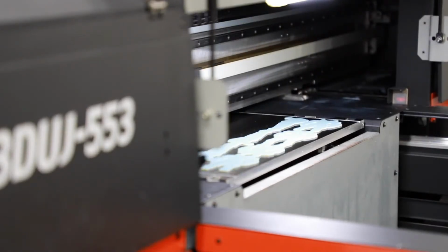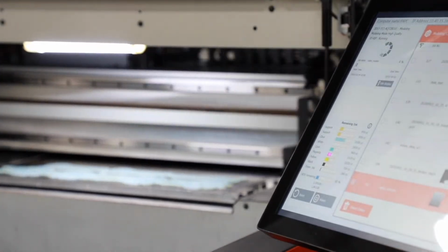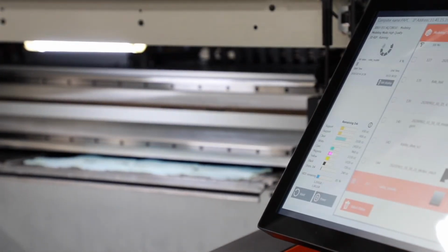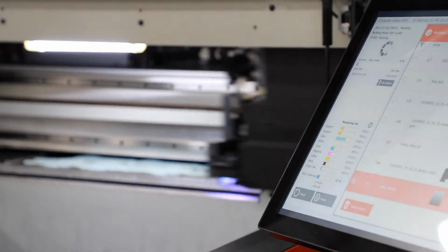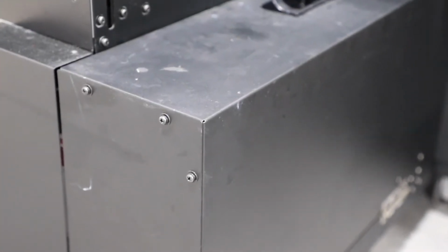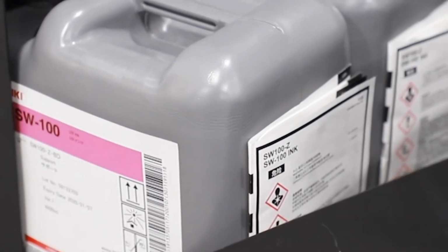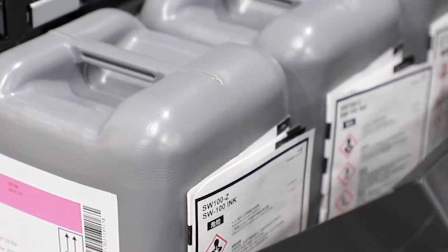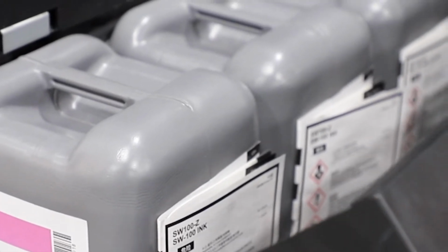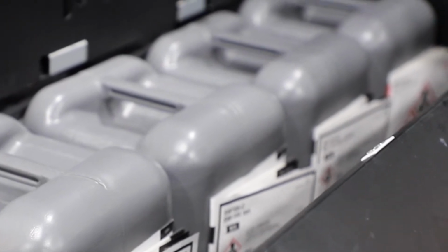Inside the machine, there's a series of 5-liter ink tanks. The printer actually prints using the resins from those tanks. This way, you're able to change the external ink bottles while the machine is running. So the resins are supplied in 4.8-liter bottles for the support material, the clear and the white, and 1-liter bottles for the cyan, magenta, yellow, and black. The bottles are put into the system along with the ink chips, and then the ink is pumped from the external bottle into an internal ink tank.